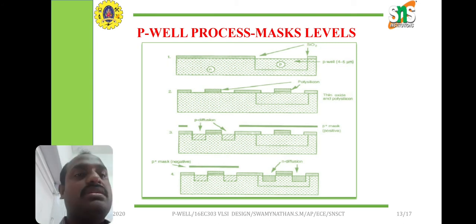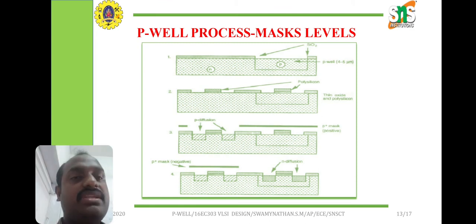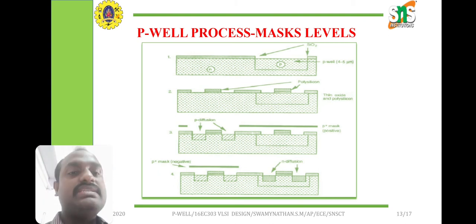The outer layer is called silicon dioxide. So P denotes pwell, and on the opposite side here we are using the N substrate. So you just remember the keyword: same diffusion, different substrate. Substrate means the other downside layer, that is called a substrate. Diffusion, how can we make the diffusion? The outer layer of silicon dioxide is heated and the gas is sent. Then it makes the junction, that is called diffusion. Based on the devices P or N, we choose the gas.